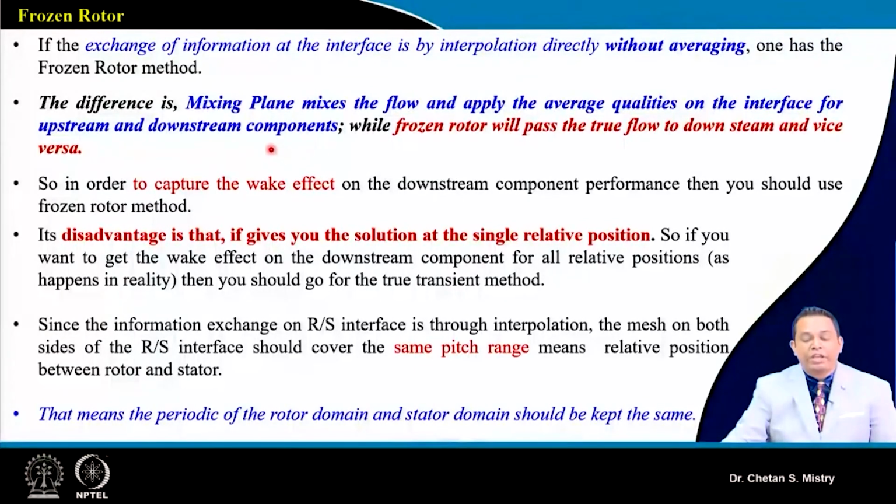The mixing plane was doing averaging at one plane, and that was transferred to the next domain, while the frozen rotor transfers the data straight away. Whatever data has been captured at the exit of my rotor plane, the same data will be transferred to the stator.